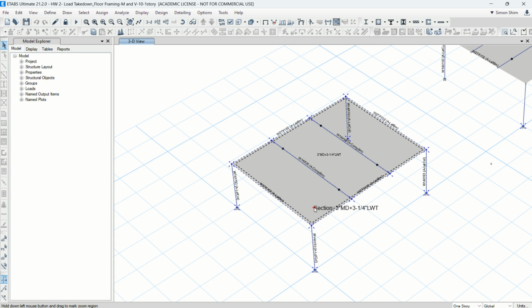And concrete is poured on top. We just assume this is a pin connection. Actually, this is not 100% pin because we have a group of bolts. We have some rotational resistance, but we just simplify. This is good enough, right? We could assume this is a simply supported beam. So this one-sided connection is a pin connection, because our connection is happening at the middle web. If something pushes it, it has a tendency to rotate here because there is not much rigidity.